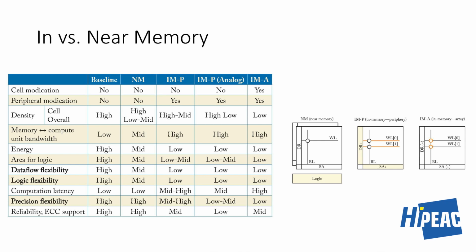So you get low bandwidth, but you get very low computation latency because you are integrating conventional ALUs outside the memory array, right? So it can be very fast. The number of cycles per operation can be 1 or 2. But if you look at in memory, it can start becoming high, because you have to do more memory accesses, you have to do bit serial processing and so on. So keep this metric in mind as we go over all the technology. It is an interesting metric.